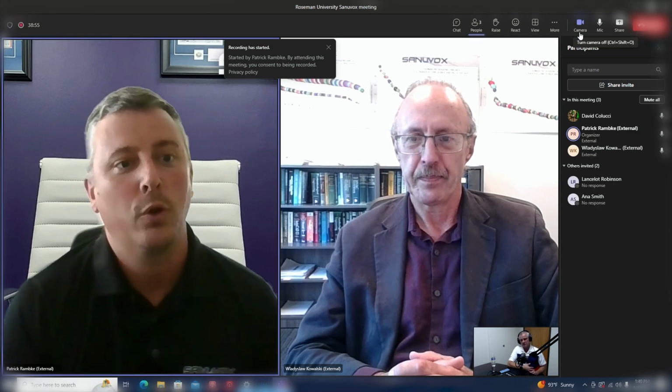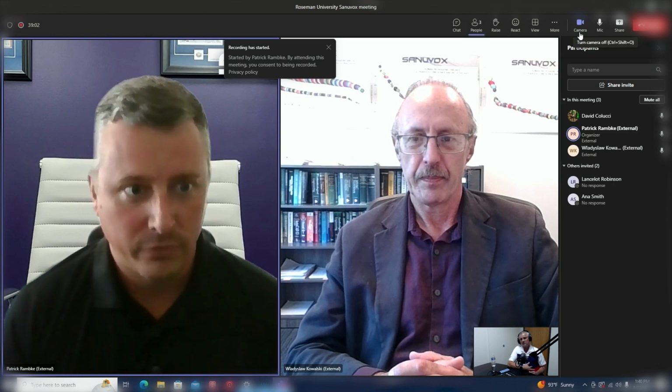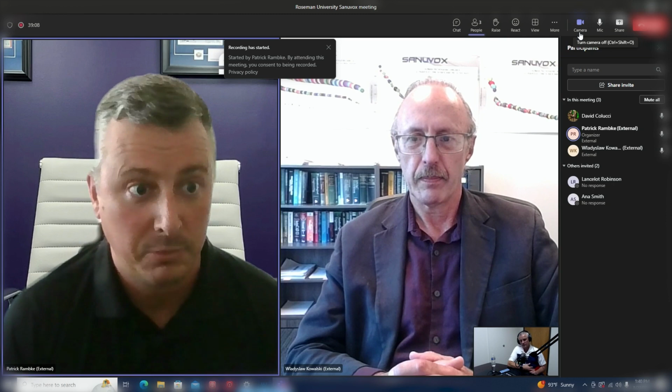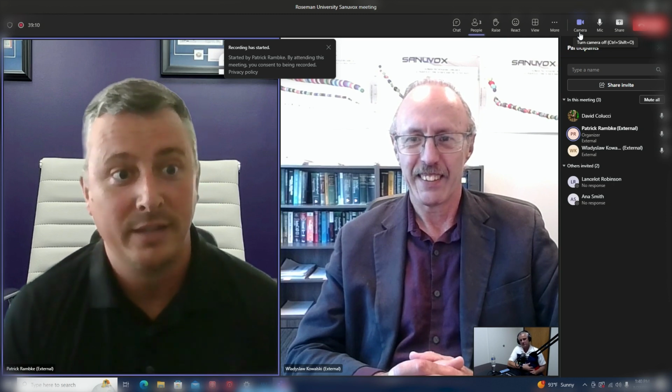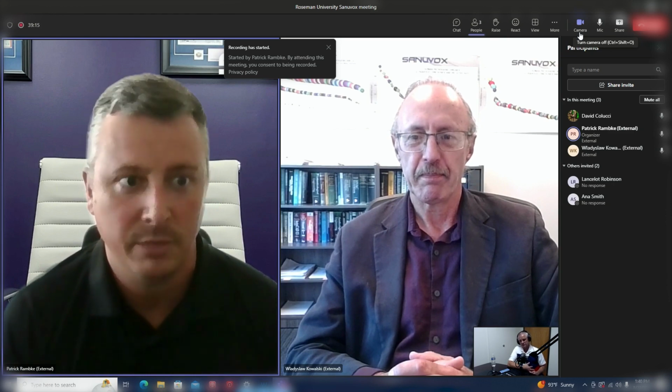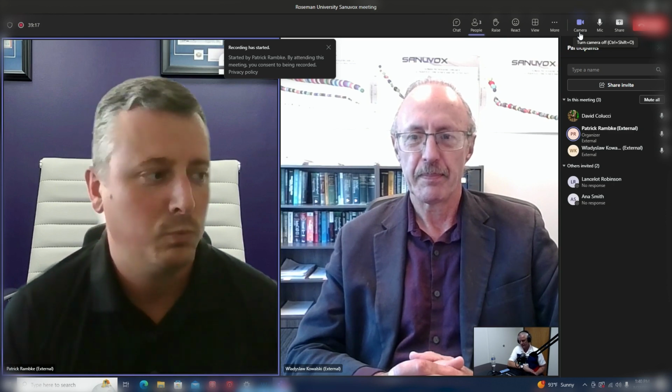to make sure systems shut off if people come into the room, or if it's essentially scrubbing the air before it's ventilated out into the outside air, for cannabis facilities who will receive daily fines from the city if the neighbors are constantly smelling the cannabis. So they have to do something about the air being ventilated out, in which case the UVV option is phenomenal. That really rids them of the problem, and it doesn't affect them negatively in any way.